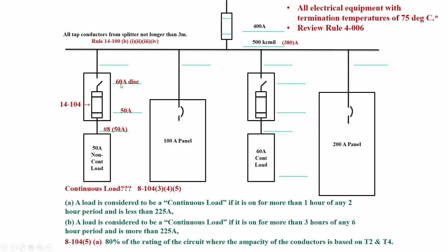So we have a 60 amp control device. All right. The next rule here, item 2, is not over 3 meters. Item 3 does not extend beyond the switchboard, panel board, or control device that it supplies. So it's terminated in there. And item 4 is enclosed in a non-ventilated raceway, armored cable, or metal sheath cable, when not part of the wiring in the switchboard, panel board, or other control device.